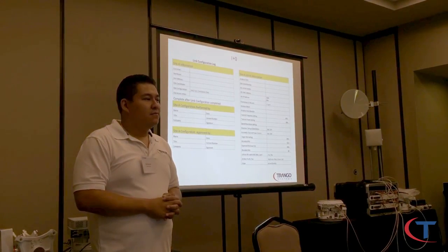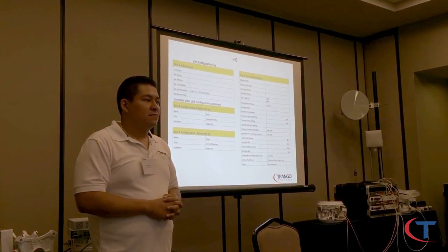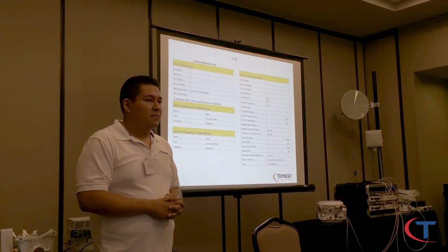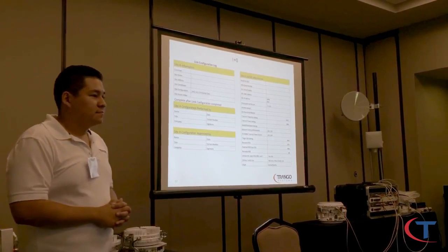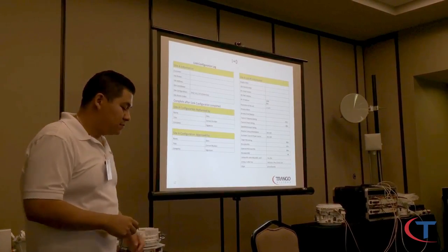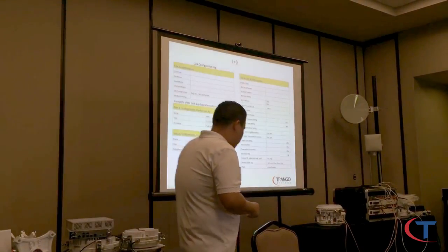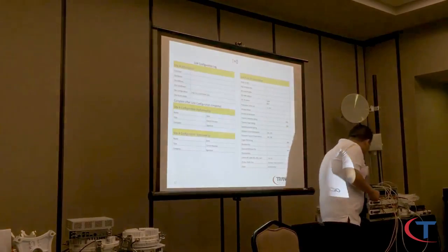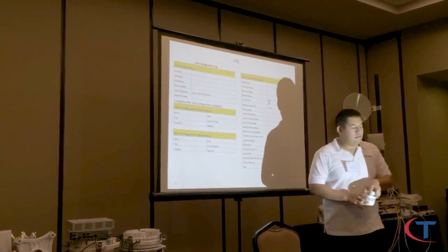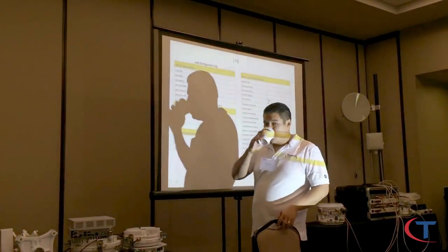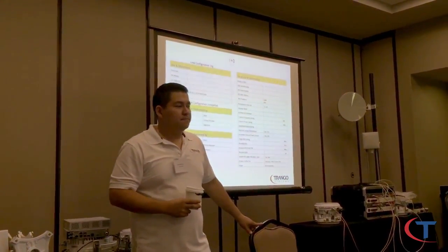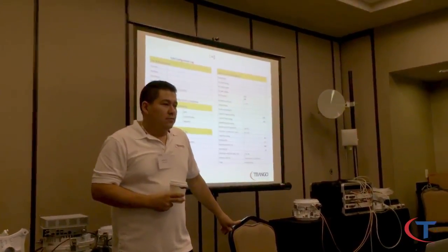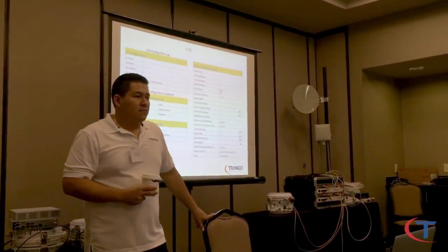Are they not actually mounted on the back of the antenna then? It's just flex? They're mounted on the pole, the waveguide, and then you've got about a 3-foot piece of flex twist waveguide going up to the antenna flange. Well, 2 flanges. If the back of the antenna starts to get tight to the tower leg, you get crowded back here really fast. A little more than a TIE fighter in back here, dude.